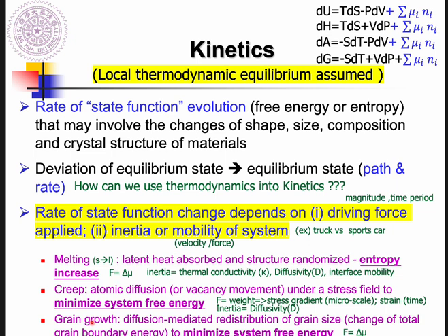If I want to decrease the portion of grain boundary, the grains will grow and the grain boundary gets smaller and smaller. That's why I say the driving force is a chemical potential gradient: with grain growth, we have more grain and less grain boundary with higher energy, so the total system energy is minimized.